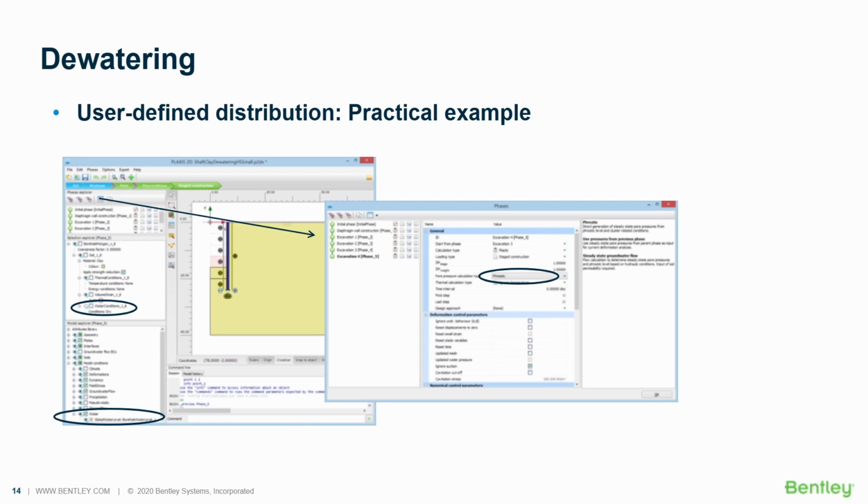on the left part here, you see, and is set to phreatic. This is the place where you start changing from phreatic to groundwater flow, okay? And this is the phase settings. Once this has been done, then you need to be monitoring carefully for each cluster, as defined in the Selection Explorer, the water conditions.